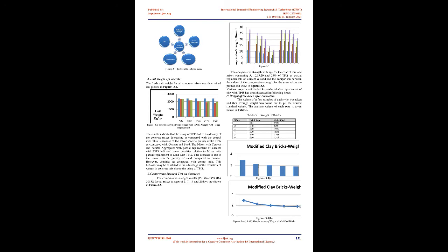All the water is removed at a temperature of 650 degrees, but the bricks were burnt at a temperature of about 1100 degrees, because the fusing of sand and lime takes place at this temperature and chemical bonding takes place between these materials after the temperature is cooled down, resulting in a hard and dense mass.